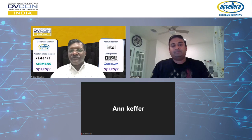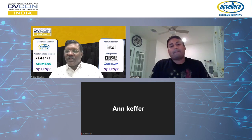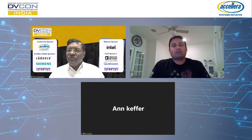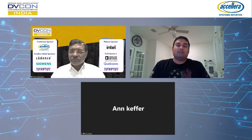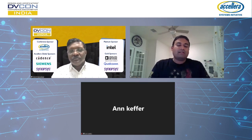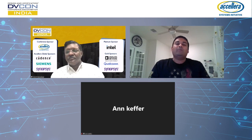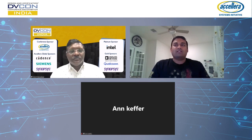Okay. Thanks, Vedant. I have one more question to go. Can you elaborate more on the fault list generation? Is the list generation based on the analysis from the previous step? How do we generate such a list from the netlist? Yes, so both our methodologies, the analysis portion and the fault injection portion, can take the RTL and netlist also. They will both be processed in the same way, and we will be able to generate the fault list on the basis of the definition of the safety mechanism.